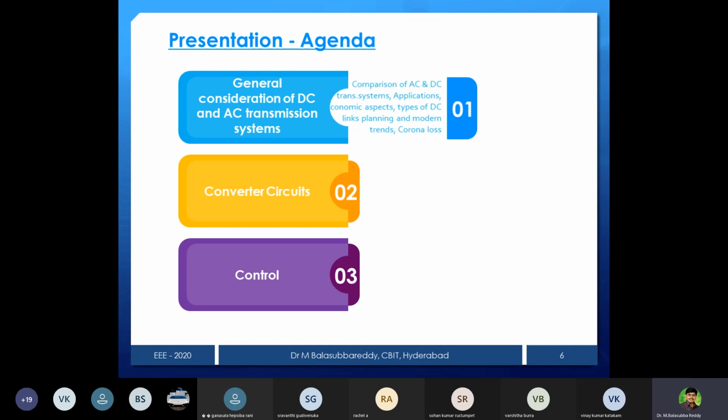There are large power oscillations, which can lead to frequency tripping in the case of AC. If there are any power oscillations or frequency oscillations, the tripping system will automatically trip, and then fault levels will also increase. So in all these aspects DC is superior. And then ground impedance also. In AC transmission, zero sequence currents cannot be permitted in the steady state due to the high magnitude of the ground impedance. All these aspects we are going to discuss.